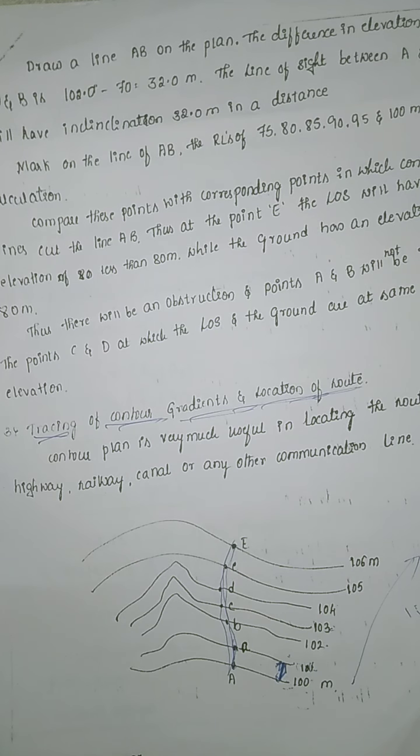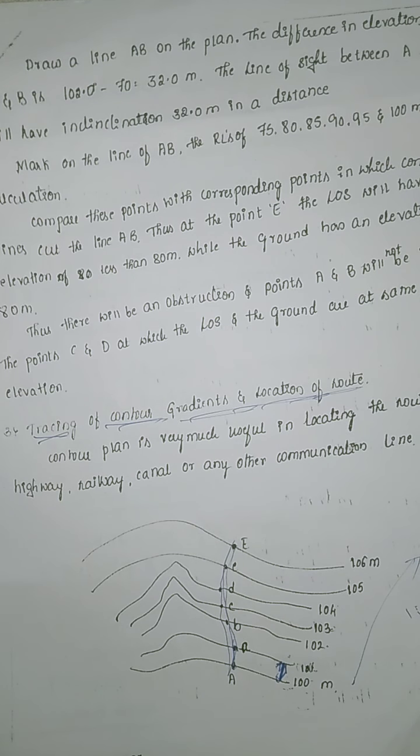It often passes through the ridges. It passes every ridge or saddle that divides the drainage area from other areas. It is always perpendicular to the contour line. As I was telling in the previous class, the drainage lines are always perpendicular to the contour lines.